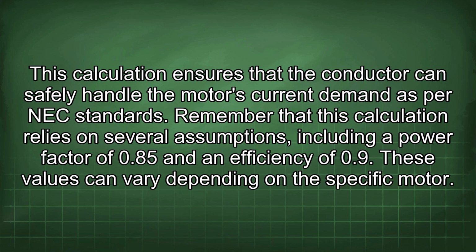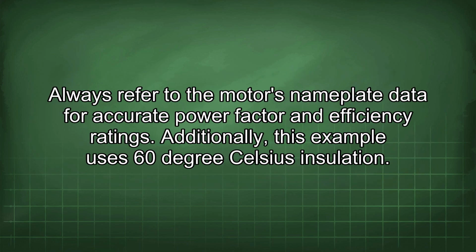Remember that this calculation relies on several assumptions, including a power factor of 0.85 and an efficiency of 0.9. These values can vary depending on the specific motor. Always refer to the motor's nameplate data for accurate power factor and efficiency ratings. Additionally, this example uses 60°C insulation.